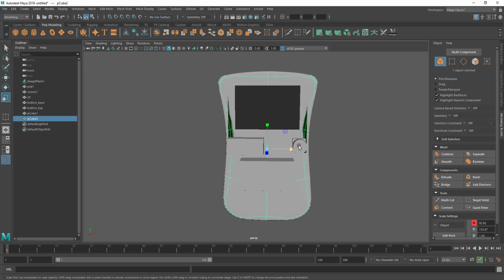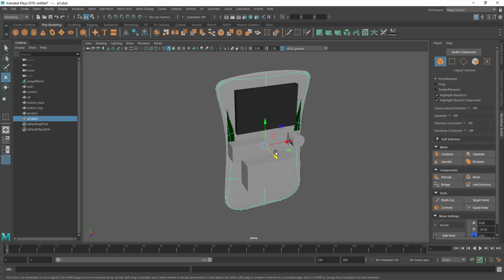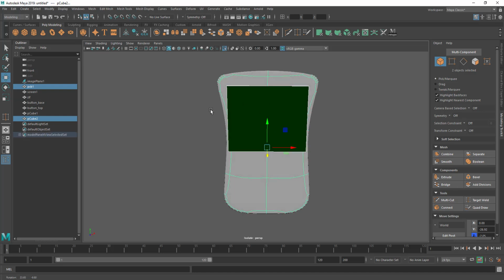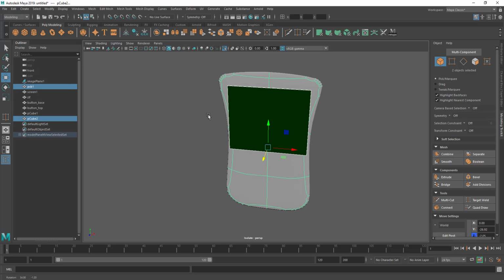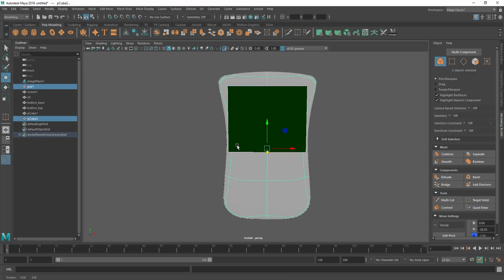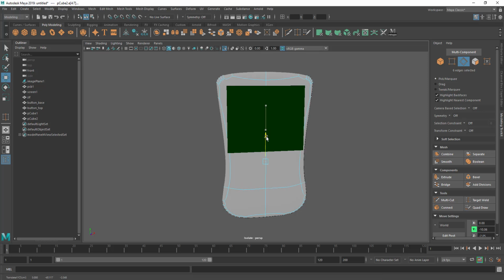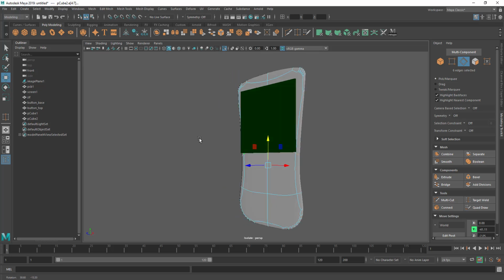Now let's have a look, bring it a bit forward. In fact, I'm just going to isolate the circuit board itself and this. I'm going to shift click on both of those, hit Control 1, and that circuit board fits in, but barely fits in. So how do we go about this? Select this edge, drag it down, select this edge. Let's have the ergonomics go a bit more like this, unfortunately.